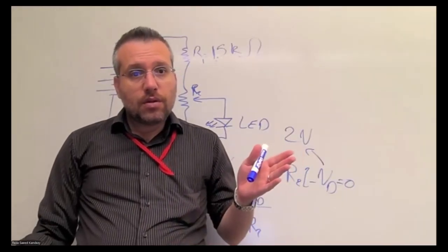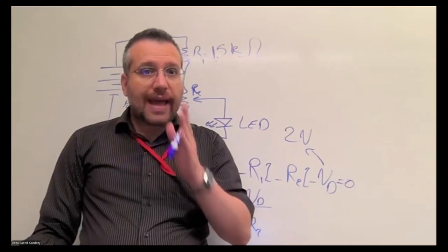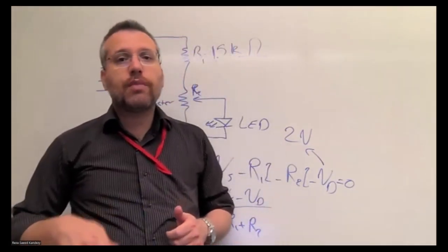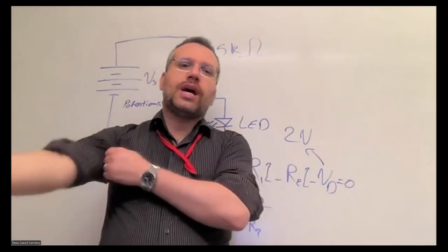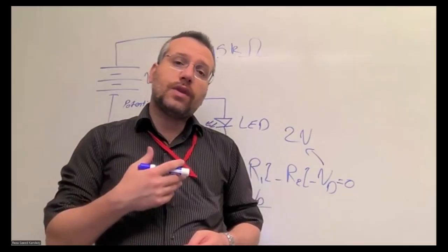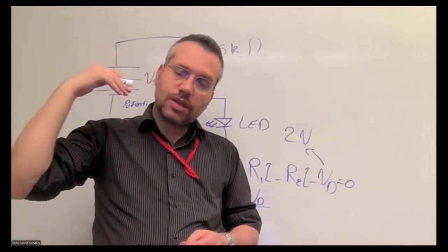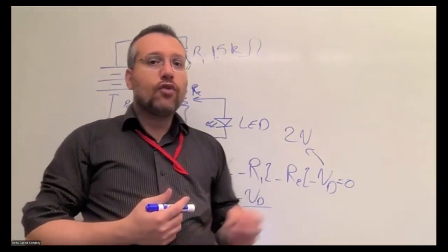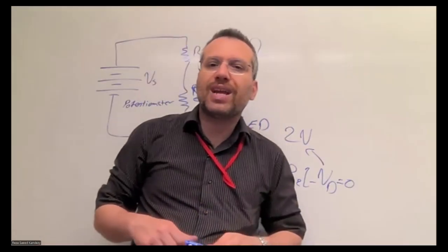Now, this is very important. A standard LED is safe only when the current goes to a maximum of 20 milliamp. So that's why we include that 1.5 kilo ohm resistor as a fixed current limiter. Even if the potentiometer in our circuit is at zero and has a very small value, we are still conservatively far under that 20 milliamp.